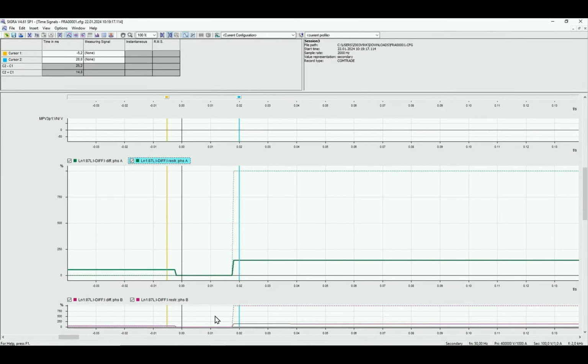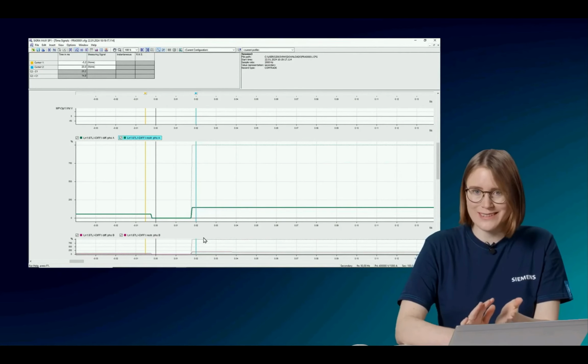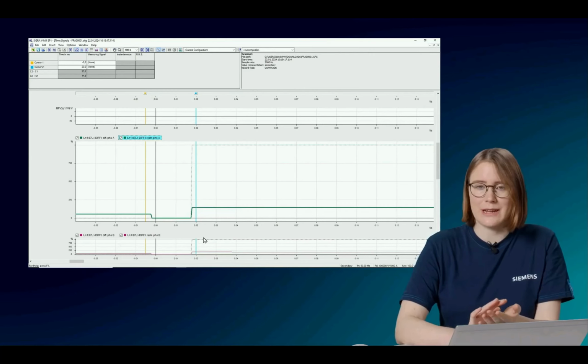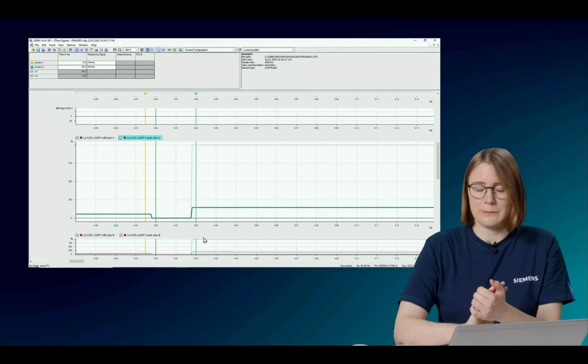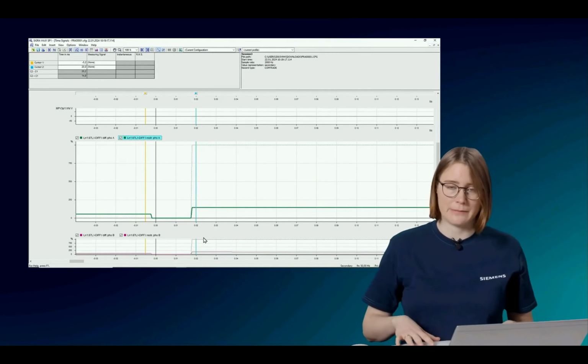And this is simply because if the relay detects a jump, then during this jump, my sensitive I differential current stage will be blocked. And we don't have to worry. During this blockage, of course, my iDiff fast stage is active. And if it is a clear internal fault with a high current, the iDiff fast will immediately switch it off. This is exactly what happened here in this example.